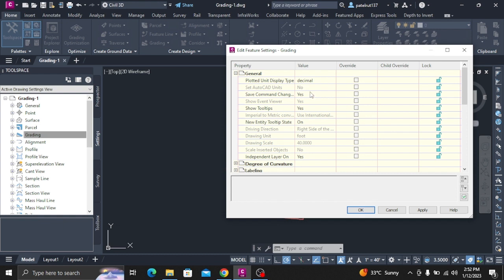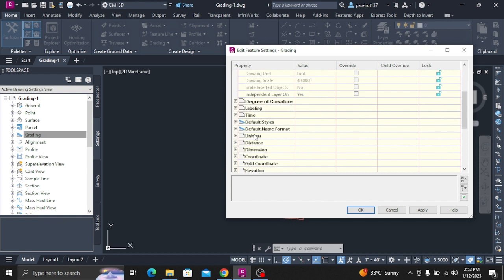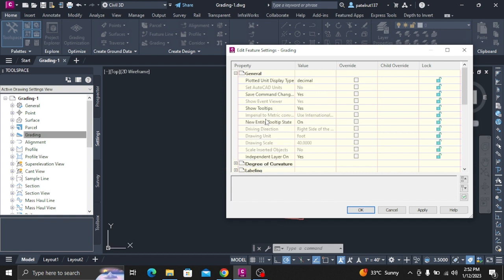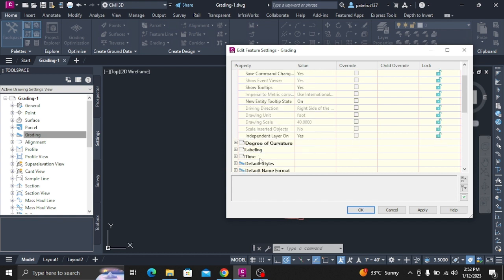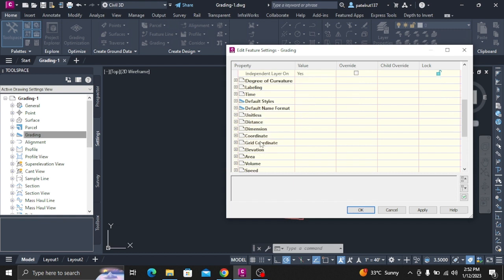Create a grading criteria. Right-click Ditch Criteria Set. Click New. In the Grading Criteria dialog box, click the Information tab. In the Name field, enter distance at -6%. This criteria creates a grade to a distance of 10 feet at -6% grade. Click the Criteria tab and specify the following parameters.